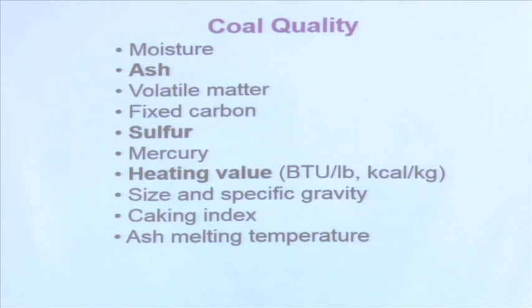But before that, if my volatile matter goes out, it does not help me anyway. So, that is also a deterrent in that case. Okay. Then fixed carbon, that means how much I am left with, that is if I subtract from 100. Suppose I have got 100 units, then subtract from that 100 the moisture, ash and volatile matter, what I am left with, we say that is approximately the carbon content of my coal.